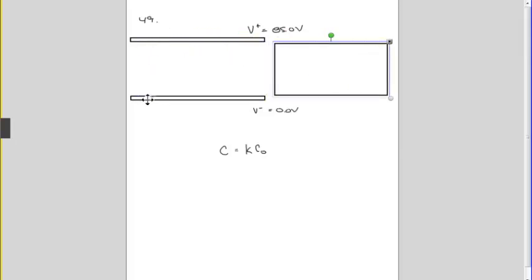So you've got a certain number of electrons on this side and a certain number of ions that don't have electrons on this side. During that period of time, we know the original capacitance is equal to the charge originally divided by the voltage. Because this is not hooked up to a battery, the charge is not going to change. So when the capacitance changes, the voltage changes, and the voltage goes down as you put the dielectric material in there.